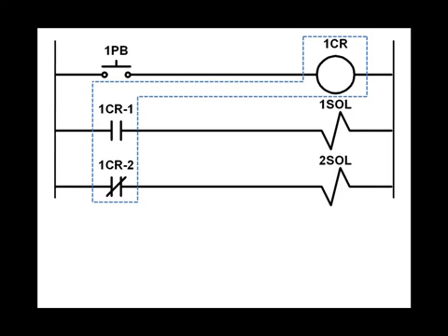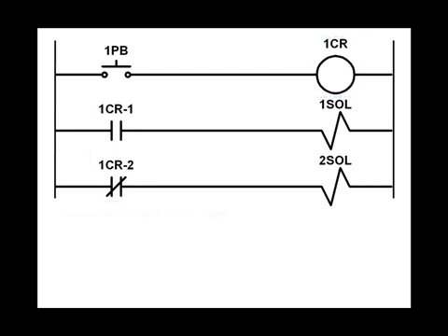In this circuit, there is only one condition or permissive in each rung that determines whether the load is energized or not. Remember that the contacts 1CR-1 and 1CR-2 are mechanically slave to the motion caused by the relay coil energizing and de-energizing. In the normal state, are any devices energized? Are any contacts true? Are any contacts false?